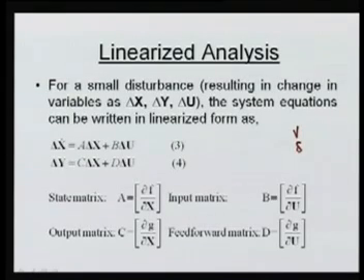For example, if you know V and delta at each bus, and you know the topology, the network configuration, and their parameters, which are fixed, we can calculate all the quantities like P loss, Q loss, the power flows in all the lines, and the reactive power flow in all the lines. So these are the things we require in any power system.